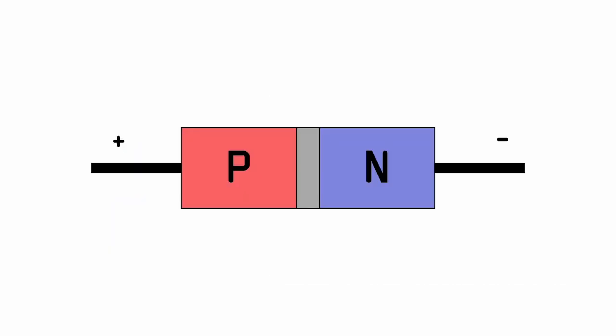So what's happening inside the diode that's making this happen? Well, inside the diode we have two chunks of materials that are put together in contact. One's called P-type material, the other's called N-type material. Now, usually nowadays they make these out of silicon, and the P-type material has some impurities put into it. It's doped, and the impurities cause there to be extra holes where electrons can go. Whereas the N-type material has impurities or doping that cause extra electrons to be present.